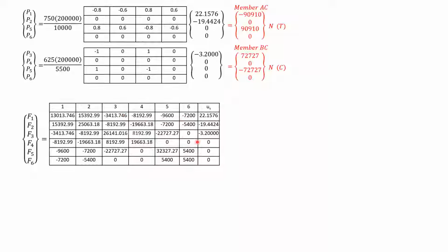So this is the overall stiffness for the entire truss. These are the displacements. So to solve for F4, F5, F6, because we already found F1, F2, F3, you can verify F1, F2, F3 if you multiply row 1 with this column for global stiffness matrix only. Anyway, you have to multiply just the first 3 rows because the rest will be 0.